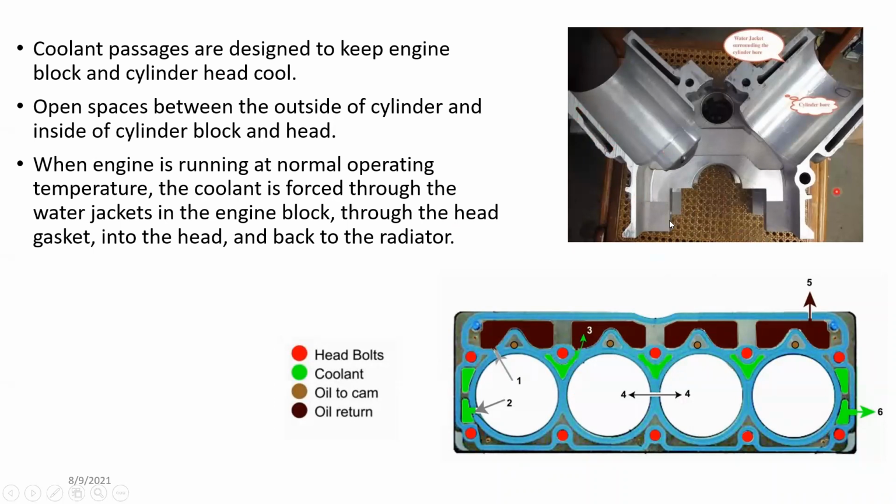This is a cutaway of a cylinder. This is a V engine. So this is your crankcase, right? These are the two cylinder walls, and you have your main journal supports, or bearings, here. Then you have the cylinder walls again. I told you this: this is your coolant jacket, or coolant passage. So it goes all around the cylinder itself.